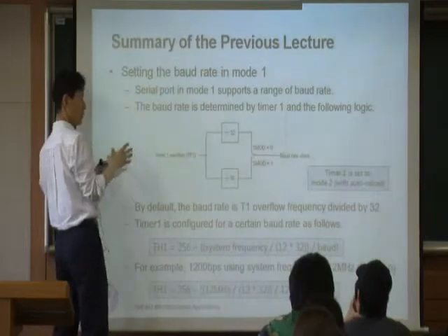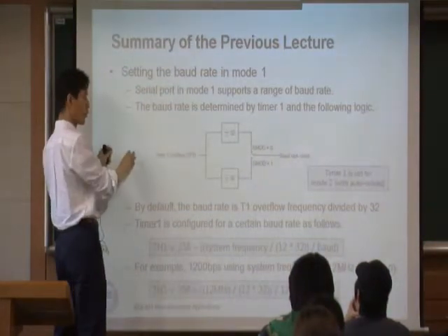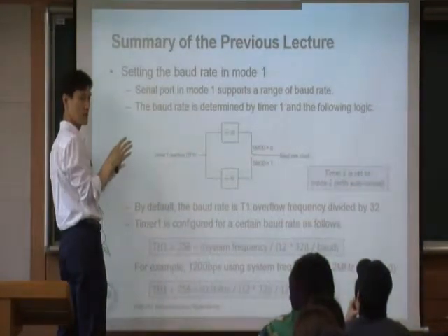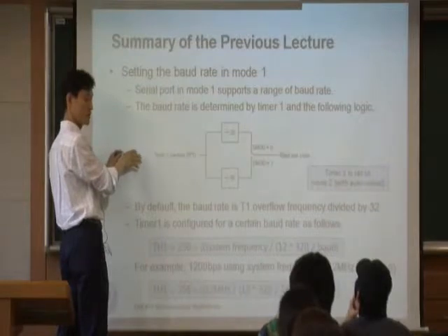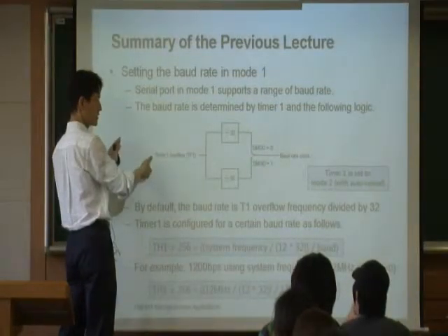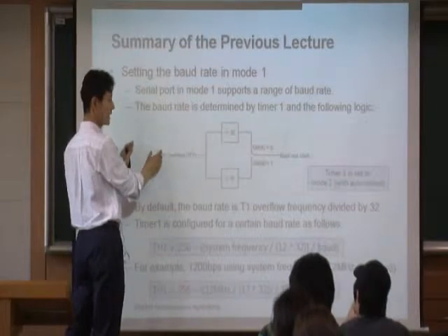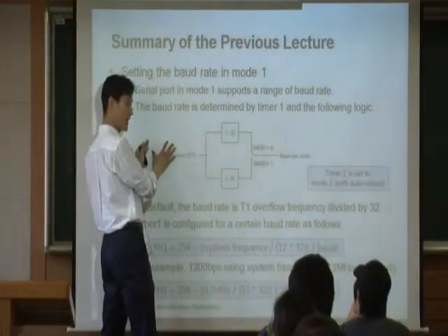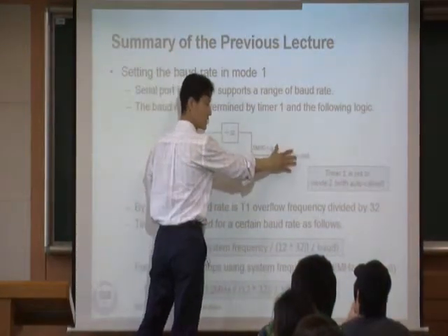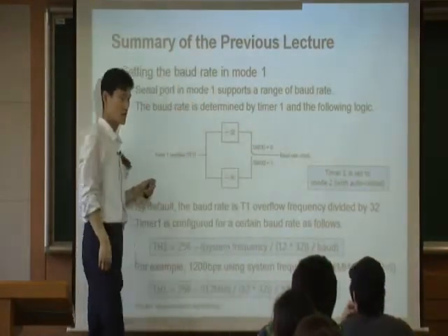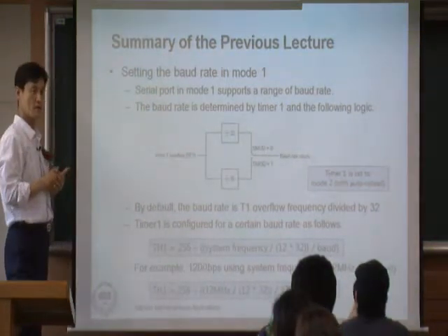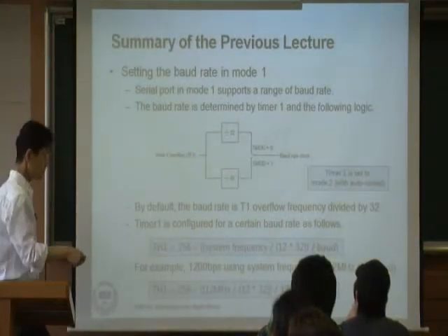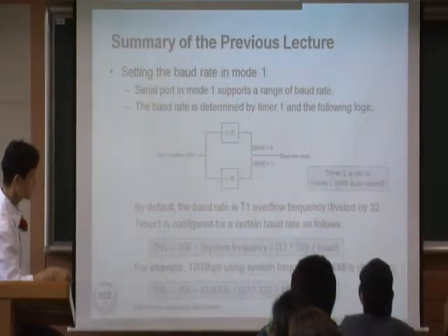Then what you want to decide eventually is what initial value you need for the timer. That's what you need to decide, right? The purpose of this timer is to create a delay of 3 microsecond. Once we have 3 microsecond of delay right here, then you're going to have 800 microsecond here. You understand what I'm saying? So that's what's happening here. So to do that, mathematically, we can calculate it this way.